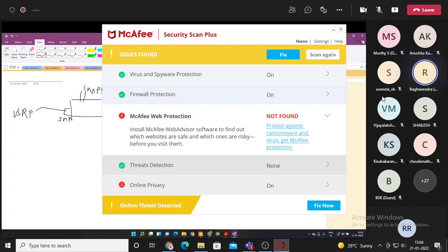A standard SMPS provides either 5 or 12 volts, but some of the circuits we've used inside require 6 volts. So what we've done is take the 12 volt to another board, where we have down converted the voltage to 6 volts. We have some voltage divider circuits over here, and from here, we give it to this PCB. I'll just name this as PCB TX.